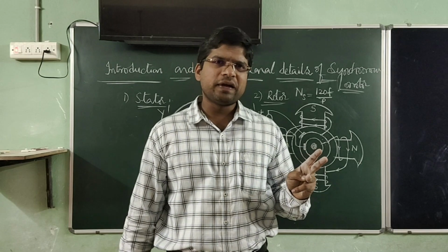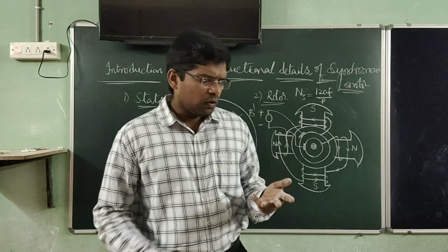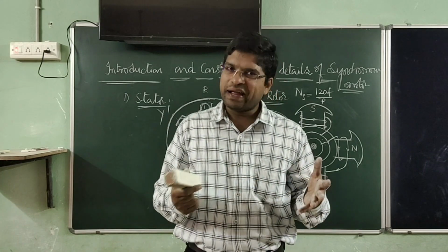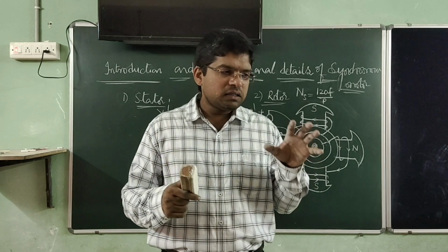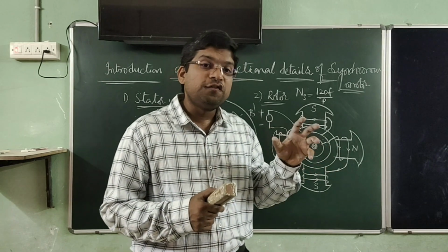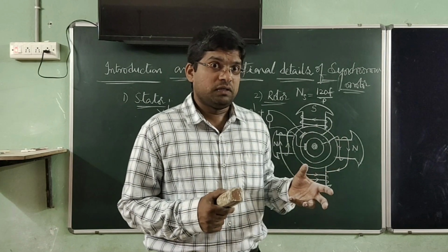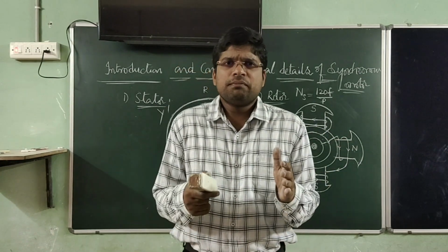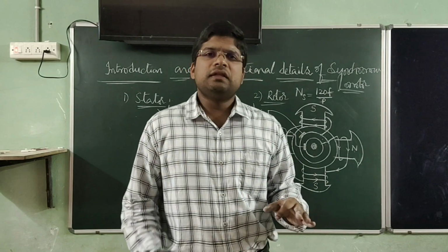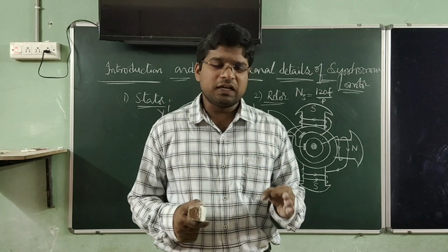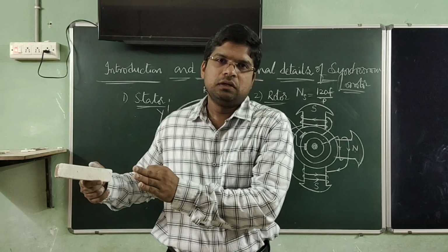At these three different power factors, we can operate synchronous motor by simply adjusting the current flowing to the field winding of the rotor poles. This is the main advantage of the synchronous motor. The second point with synchronous motor is that it can be operated at different power factors.